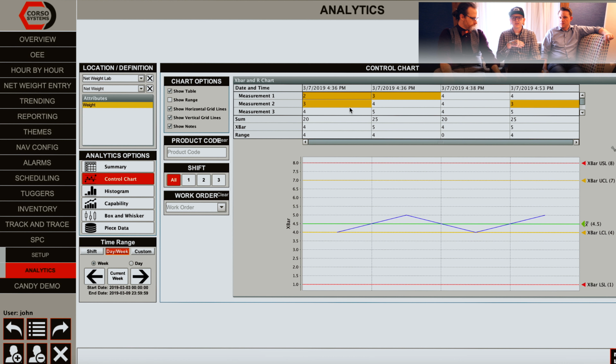Yeah, if parts come off the line and identify them as good within OEE, but then a quality inspector maybe 30 minutes after those parts are produced, if they go into a box and pull 5 units out and they test them and they find that 1 out of the 5 is bad, then they go back through the rest of the lot or the production order and they find additional units. We can identify that in these tests when we're relating these parts to a specific work order, and we can decrement and update that quality level accordingly with OEE. So they do kind of go hand in hand and integrate well with each other.